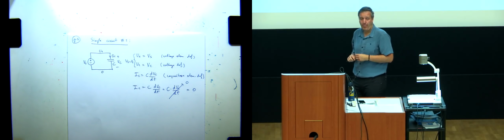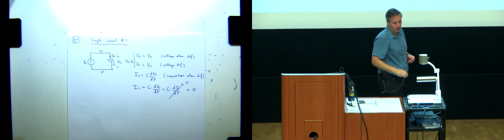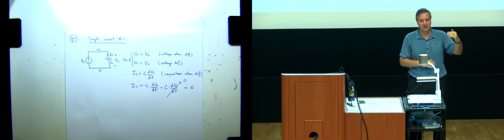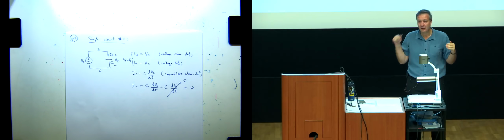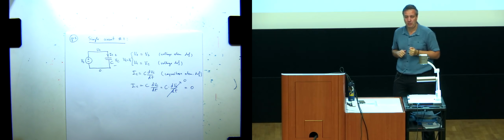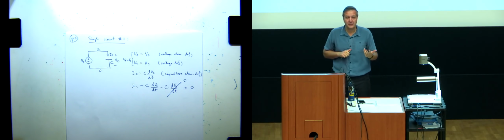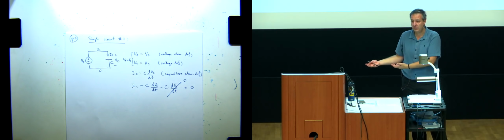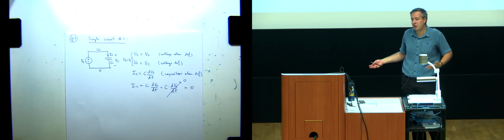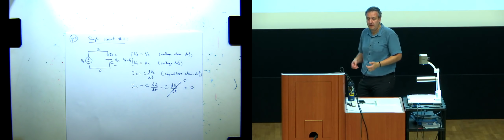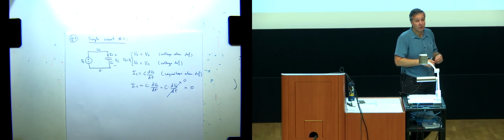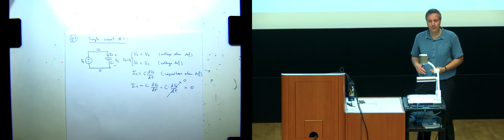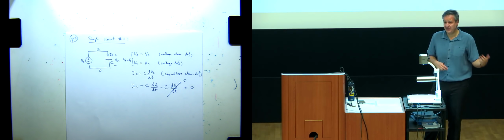That's puzzling. So what this tells you is that whenever you have a constant voltage across a capacitor, the current of the capacitor is equal to 0. Right? And the reason is that by definition, the current on the capacitor is the slope of the voltage across the capacitor. So if the voltage is constant, the slope is 0. Right? Does that make sense? This is actually a really important thing that we're going to use throughout a lot of these capacitive circuits to make our life easier.